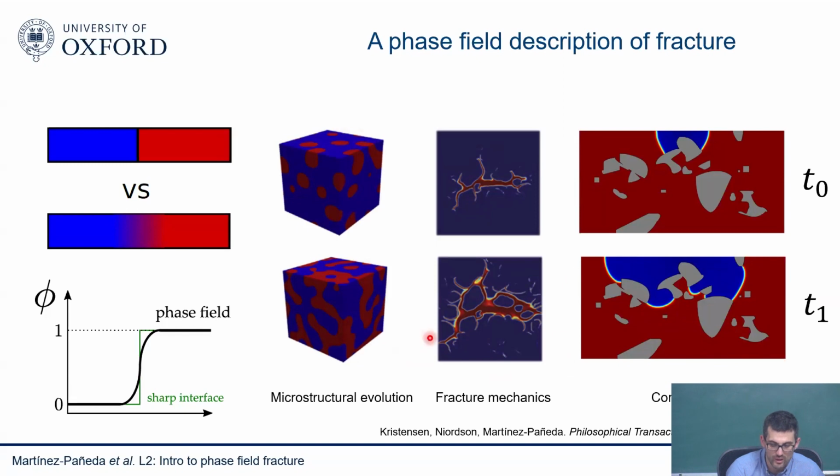It is becoming very quickly the dominant technique in fracture mechanics, in computational fracture mechanics. And you can see why here, right? Red color means crack, blue color means intact material. This is the outcome of a simulation for a hydraulic fracture problem. So fluid-driven fracture, that's why you see such a complicated cracking pattern. And these are, by the way, results, I think, from Ibonet's group. And you can see that very complicated cracking phenomena can be captured. You have coalescence of multiple cracks, initiation of secondary cracks, crack branching, crack coalescence. It's really very nasty cracking business that before we had phase field, there was no way we could capture such a thing. No way. So you can see why it's becoming quite popular.